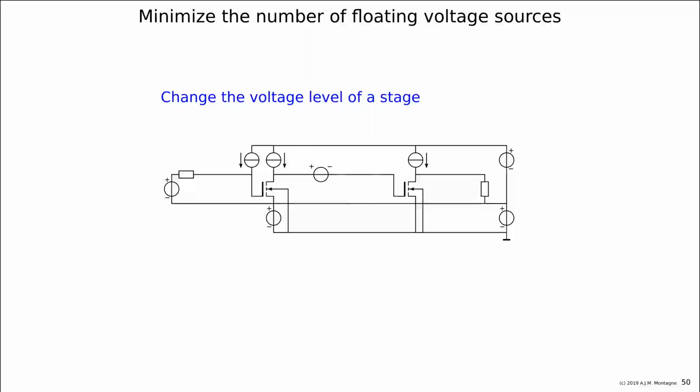The output port bias was predominantly important. The current was predominantly important for that, not the voltage. As long as the transistor can handle the voltage swing there, so it doesn't go deep in the linear range where the amplification really drops, then any voltage is okay, because the drain voltage does not largely affect the behavior of the transistor, the noise, and of course the voltage drive capability.